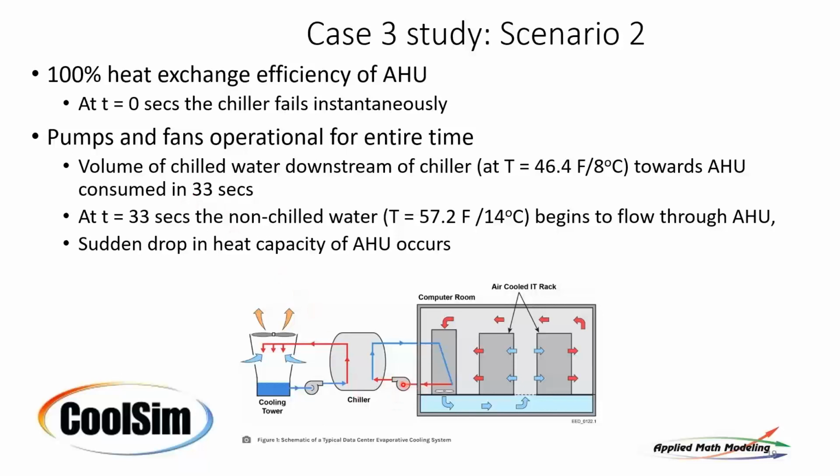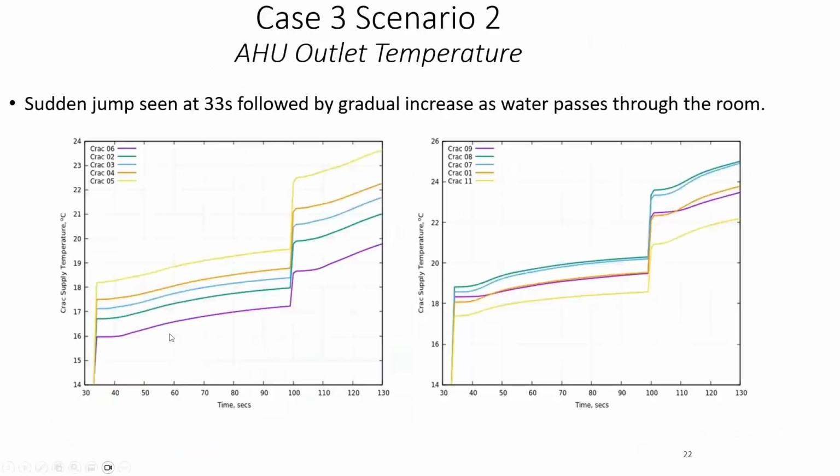In other words, you really only have a shot of water from this. Well, I'm going the wrong way. Yeah, from this device over to these, that's half the loop. So that's 33 seconds, and then it comes out hot and heads back. Therefore, you get this step, and this is kind of an interesting situation. You have temperatures rise because the fans are off, and then you get a slug of water that comes through. And that provides some level of cooling.